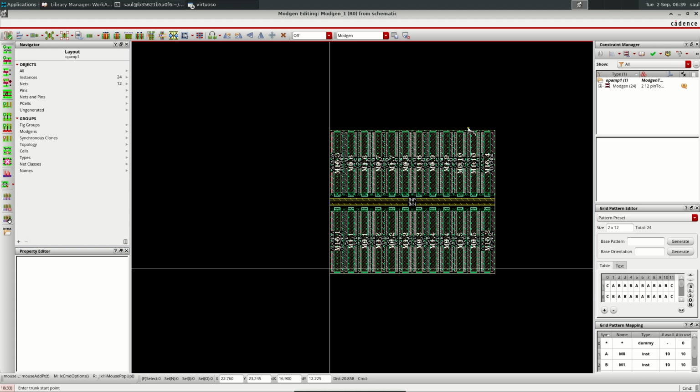So we have to be a little bit more careful with this layout of the source than to the drain. An impedance that is added to the drain is not normally so problematic. So we are going to lay out the source first because it gets closer to the transistors.